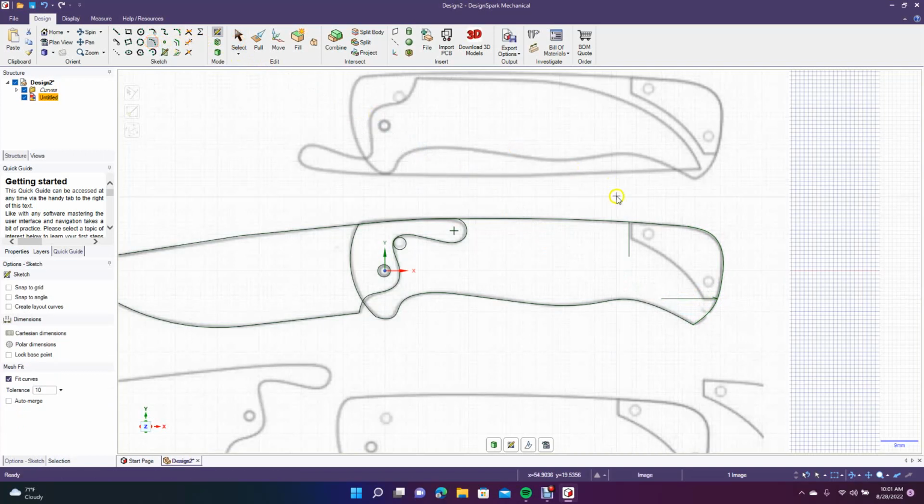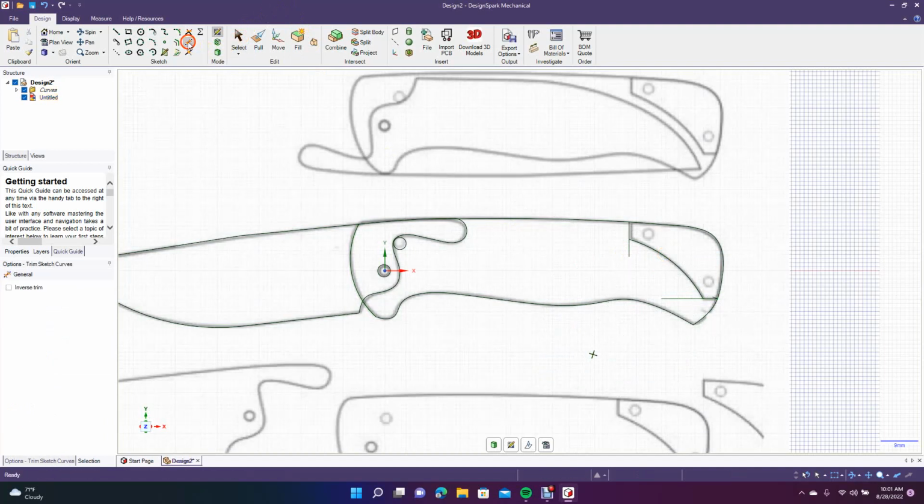Get your 3-point arch. I'm going to go from there over to here. And then give this click. Give that line a little curve in. Alright, select, click off. Get your trim away tool. Let's trim these. Get rid of that little piece there.